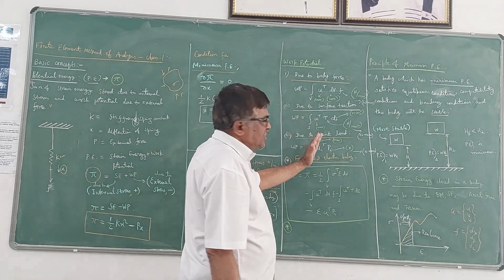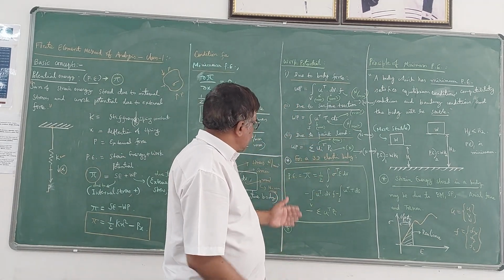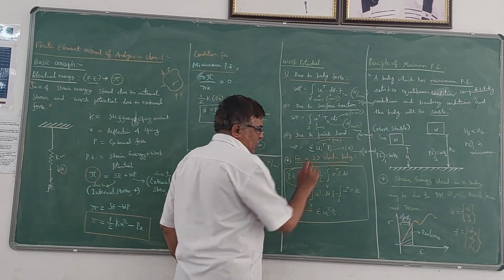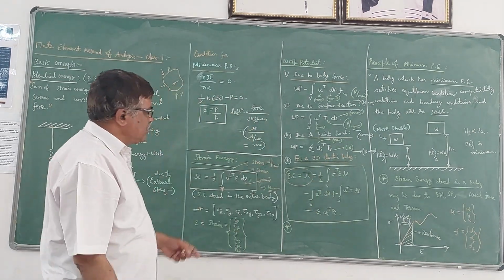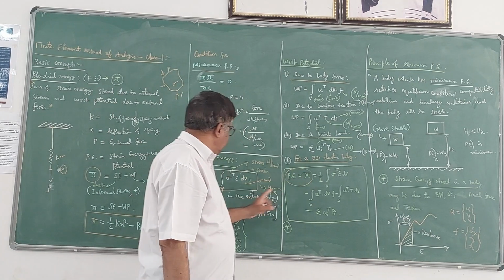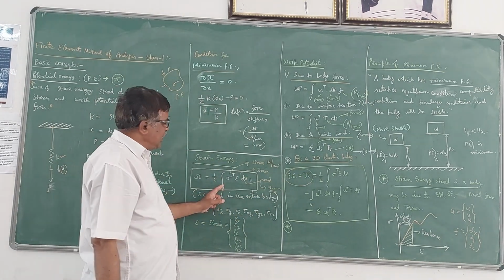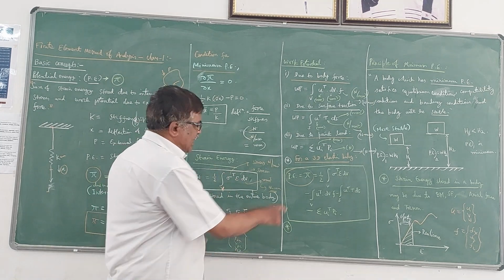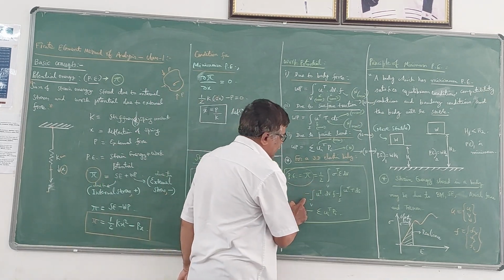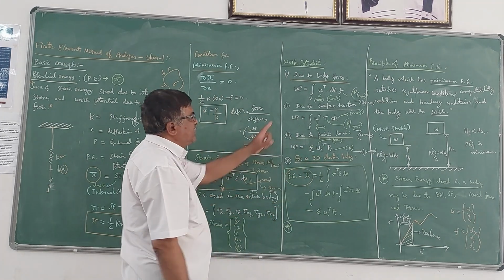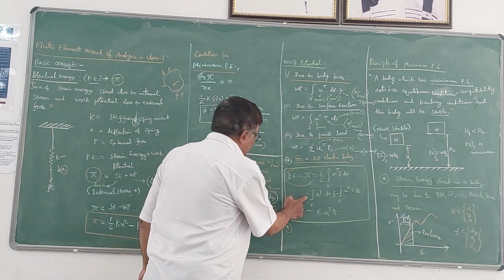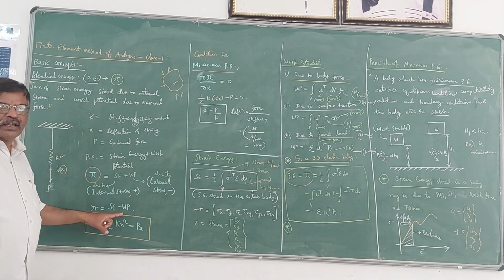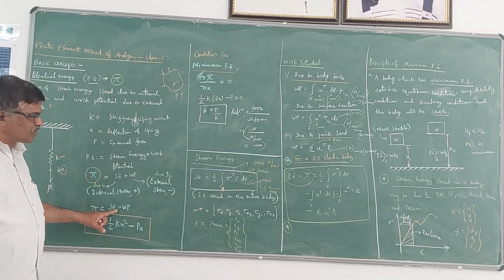Now if you combine all these three, body force, surface traction, and point load, you can express the total potential energy in a three-dimensional elastic body as half into integral over V of sigma transpose into epsilon dV, that is the strain energy part, and the work potential part will have 3 terms. I have taken them negative because work potential is opposite in nature to the strain energy.